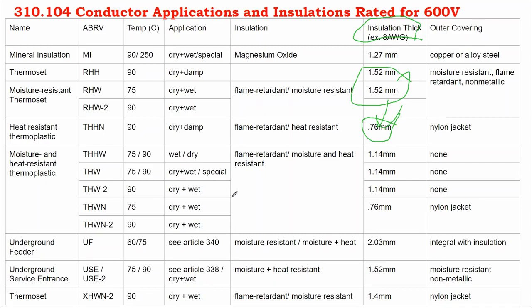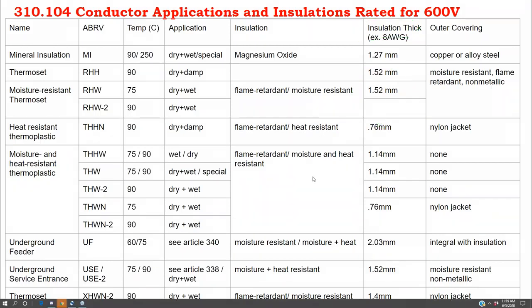And furthermore, that thicker cable jacket inside that conduit is going to retain heat in the cable a little bit better. So by and large, you want to use indoor cable inside and you want to use outdoor cable outside. Maybe for a very short run, sure.